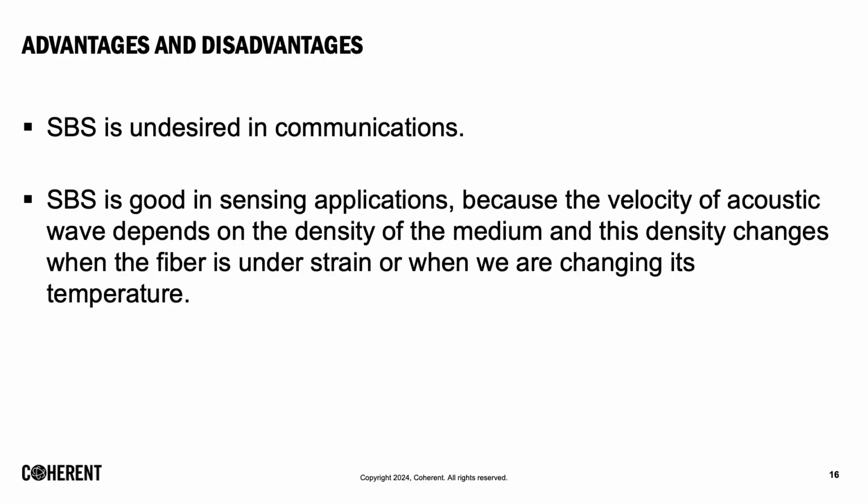So to finalize this presentation, I would like to say what are the advantages and disadvantages of SBS. So depending on our application, SBS can be good or undesired. So in communications, we don't want it because it limits the amount of power that we can put in the fiber. But on the other hand, it's very good in sensing applications. That's because the velocity of the acoustic wave depends on the density of the medium. And this density changes when the fiber is under stress or when we change the temperature. So that makes a very good sensor.